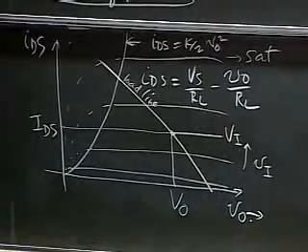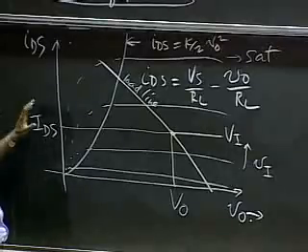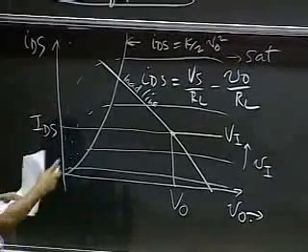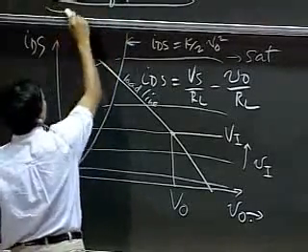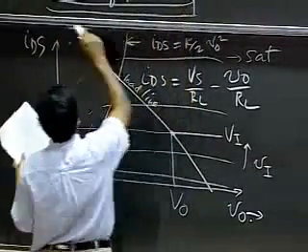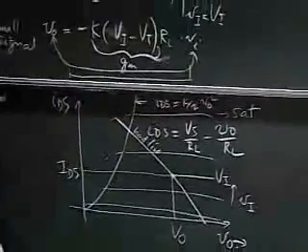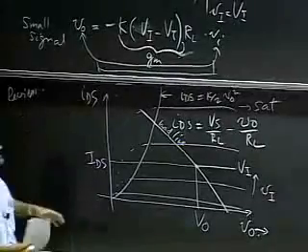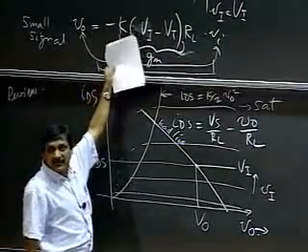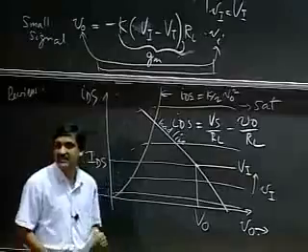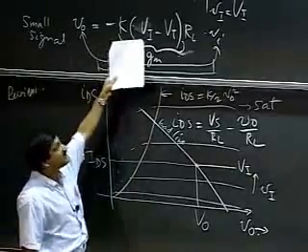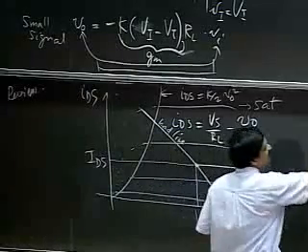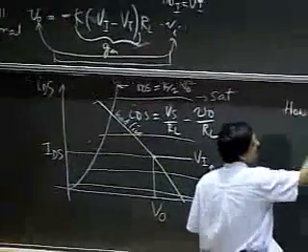One thing we stopped the last time by pointing out is the gain of our amplifier. This is the gain, minus K (Vi minus Vt) RL, that's the gain A of the amplifier. That gain is related to Vi. The gain is proportional to Vi minus Vt. So therefore, if I increased Vi, I would get more gain. So the question is, how do we choose a bias point?